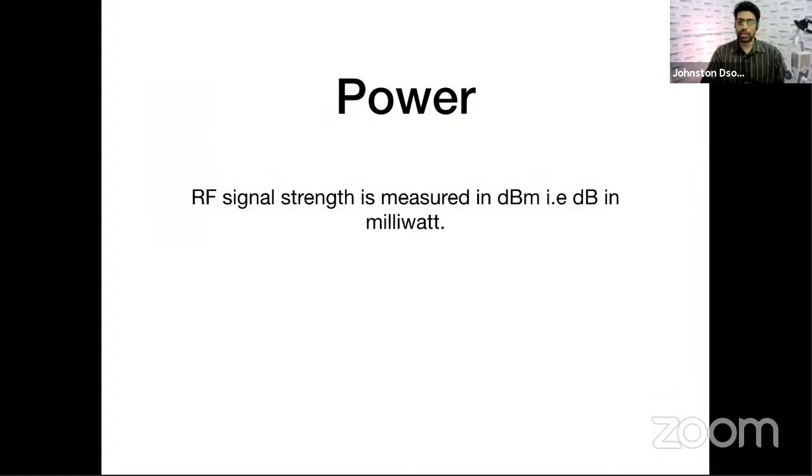I'm only going to explain to you FM because that's what is majorly used. Only some digital, like the Sennheiser 6000 series and the Shure Axient Digital, are going to be used. Instead of sending an analog signal, they're going to be transmitting digital data. And the way they do that is slightly different. You can go and check it out. They basically use phase shift keying and amplitude shift keying, 2 different kinds of modulations they use to send digital data across.